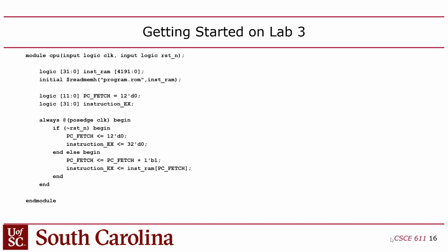Okay, then what? Obviously, I haven't added the switch input or the output for the hex displays, but we'll add those later. What's the next step? The next step is the instruction RAM and the clock. I mean, the PC, program counter, right? So the clock is kind of the heartbeat, and the program counter is going to be a counter sequence that pops out, and then that counter sequence goes into the instruction RAM.